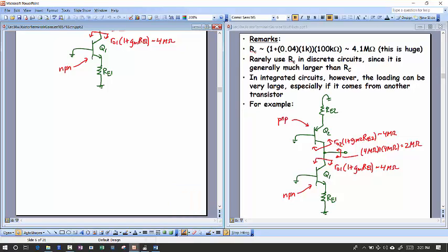We got the gain for a common emitter amplifier. What I'm talking about now is getting a gain for this generally loaded transistor that now has resistors around it. The emitter is not going to ground. It's going to ground through a resistor. So let's do that. Let's get what I'll first call base to collector gain.